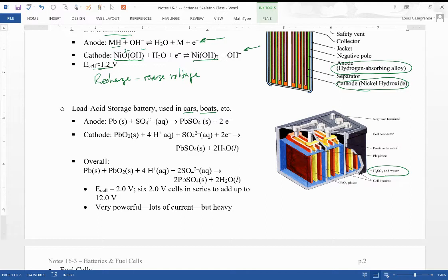And when you jump-started it, if there was hydrogen gas present and you got a spark as you connected the jumper cables, you could ignite that hydrogen gas and cause an explosion. Unfortunately, many people received acid burns from exploding batteries because they jump-started the batteries incorrectly. So those of you who are taking driver's ed, if you've learned how to jump-start a battery, be careful. Just connect the cables in the correct order, and you should be fine.